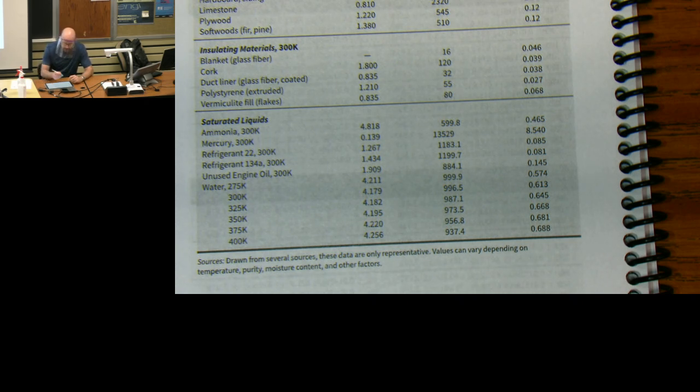Okay, so what do we have? Inside our system we have two things. We're going to have the delta U of our water plus the delta U of our iron equal to 0. We're going to expand these. This is going to be the mass times the internal energy 2 minus internal energy 1 of my water, plus the mass of my iron times the internal energy 2 minus internal energy 1 of my iron, and that's going to equal 0.